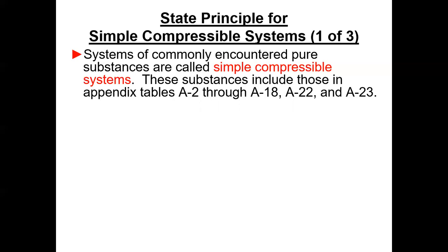So, for example, moist air is considered a binary mixture of all the dry gases and water vapor. And so it turns out that we have to have 3 independent properties in order to determine a state, and then all the rest of the properties can be determined from those. So anyway, that's kind of where we're going in this.